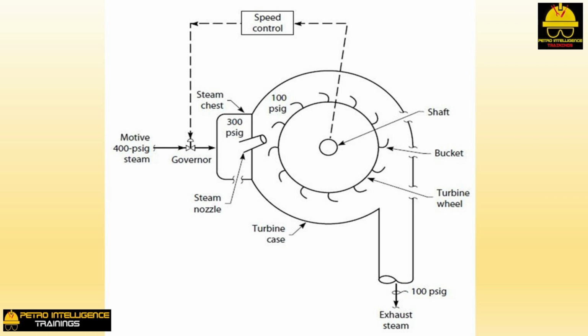If you are using your Mollier diagram, you will have noted that the temperature of the steam has dropped from 375 degrees Fahrenheit to 220 degrees Fahrenheit. The 220 degrees Fahrenheit is the temperature of 17 psi as saturated steam. That 155 degrees Fahrenheit drop in the steam temperature represents 85 BTU per pound.